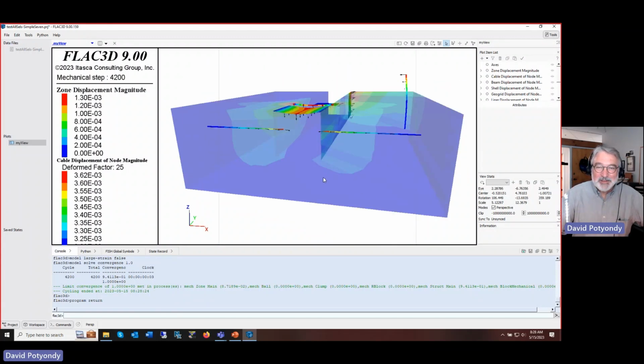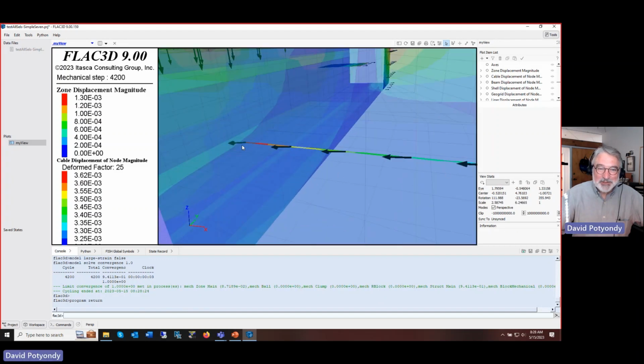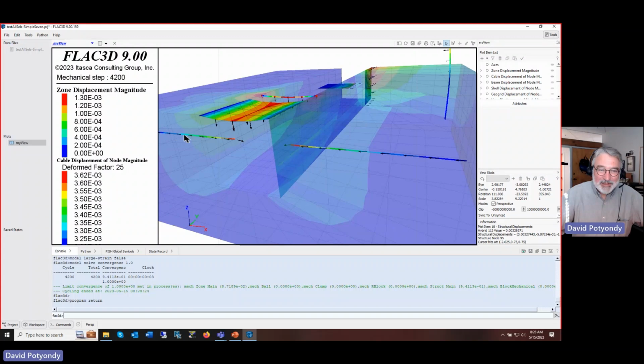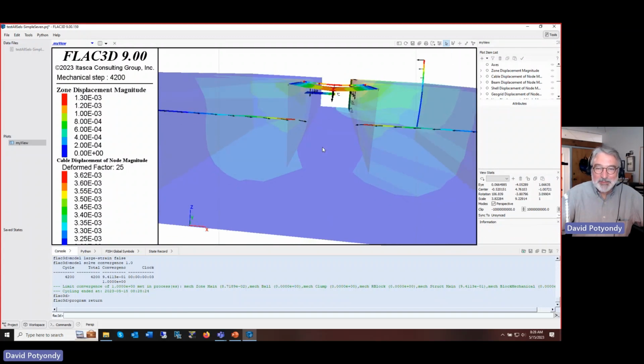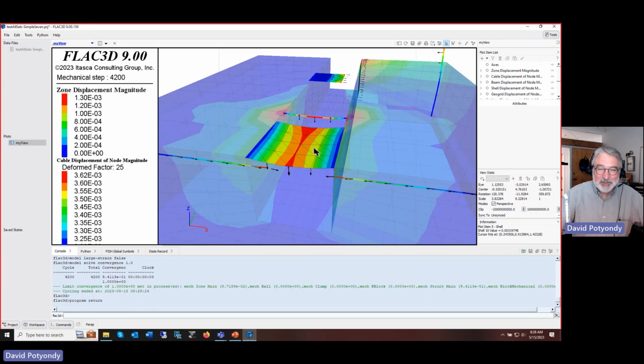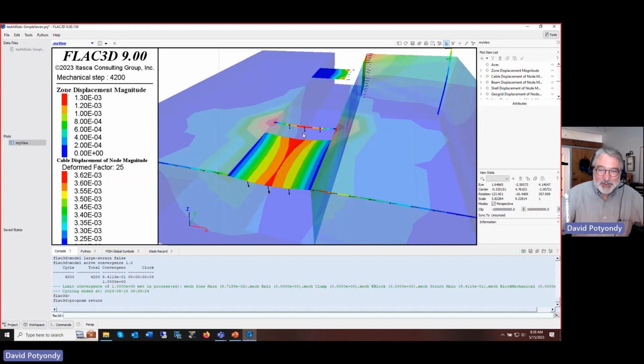And you can see what we've got here. We can see that this cable got pulled. That hybrid thing got pulled. There was a uniform pressure on top of that shell. You can see how it's deformed. I'm plotting contours on the deformed shape. I'm using the vector plot item to show those nodal displacement vectors.